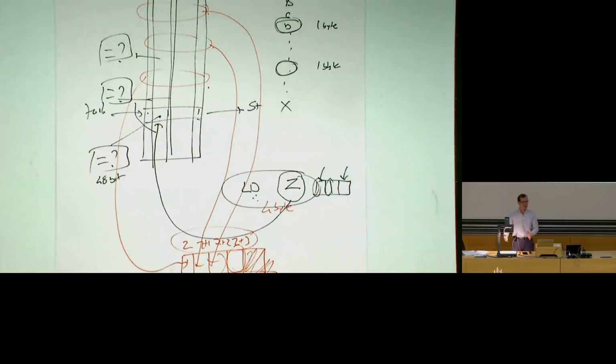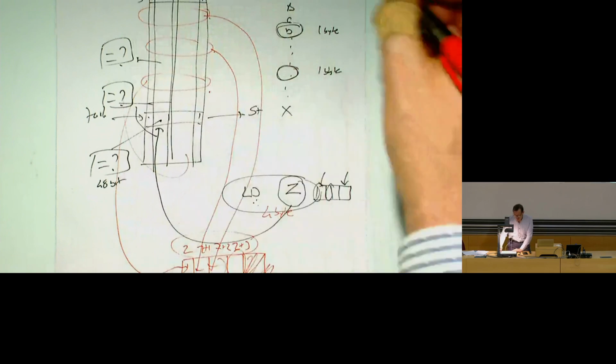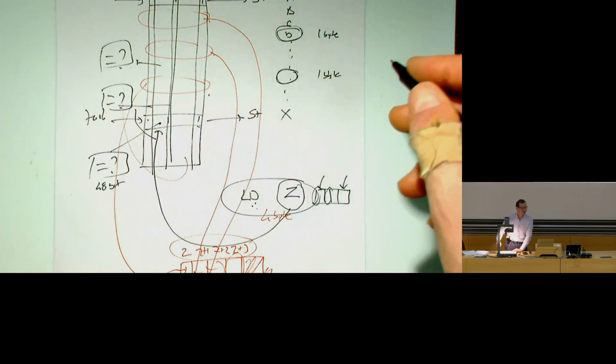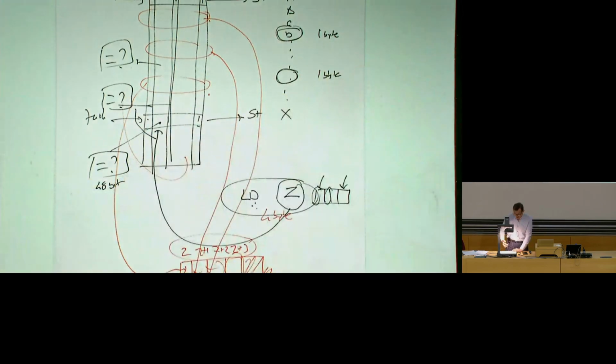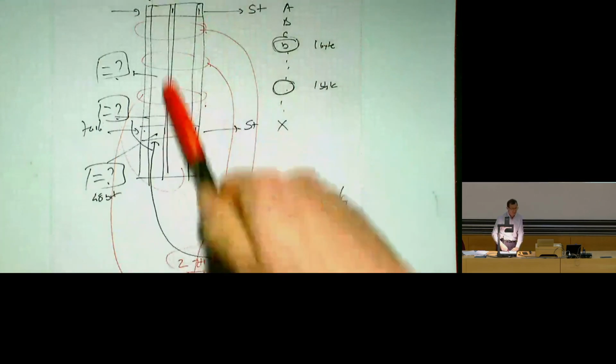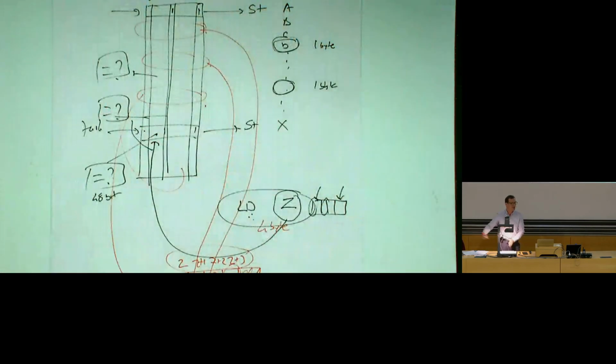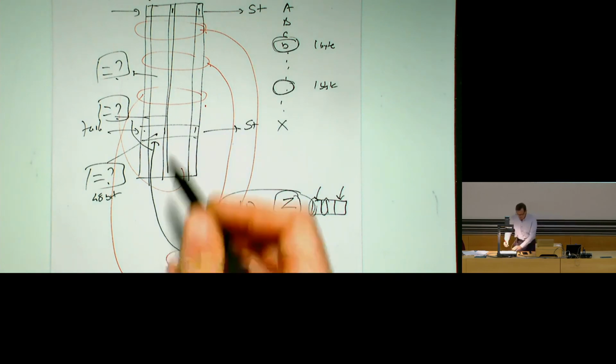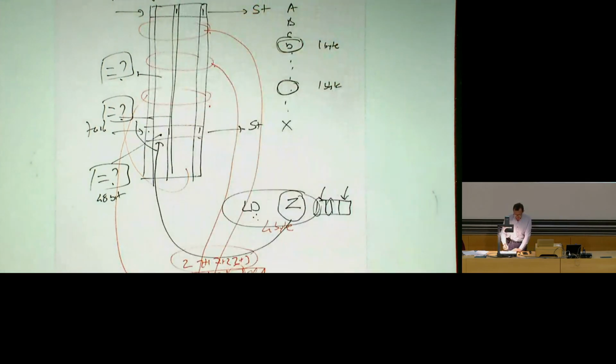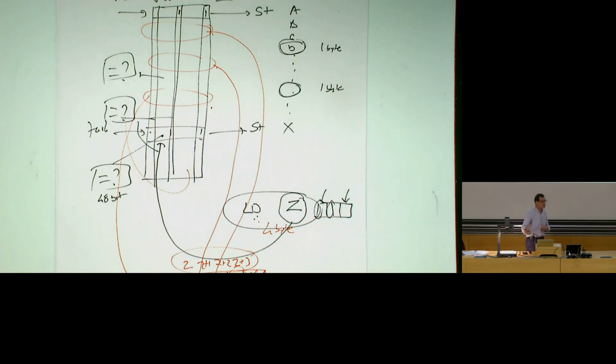So to be able to get your data value, you need to search this, and you also need to access memory. That's why this is one of the most complicated parts. And when you search this, of course, there may be no match. Then you access memory, of course, to get all of it, right? Because there may not be any stores that are writing to the location that you're reading. At that point, you need to access memory. So this search may be useless, but you need to do it to ensure that you get the correct value for the load.